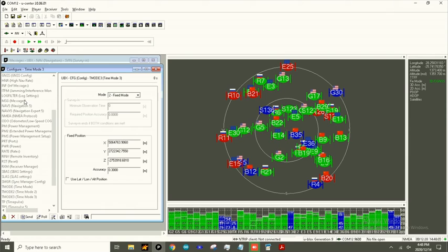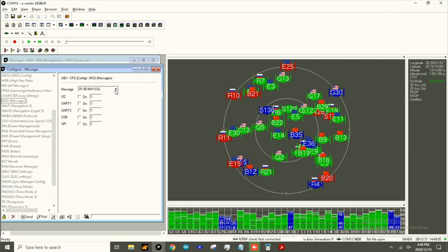Moving back to our messages terminal over here, first thing we're going to ensure is that the RAW-X measurements have been disabled from the previous example. Even though we did reset the GNSS receiver, we can still just confirm that that is in fact the case. And there we see that we have no RAW-X messages enabled, which is correct.